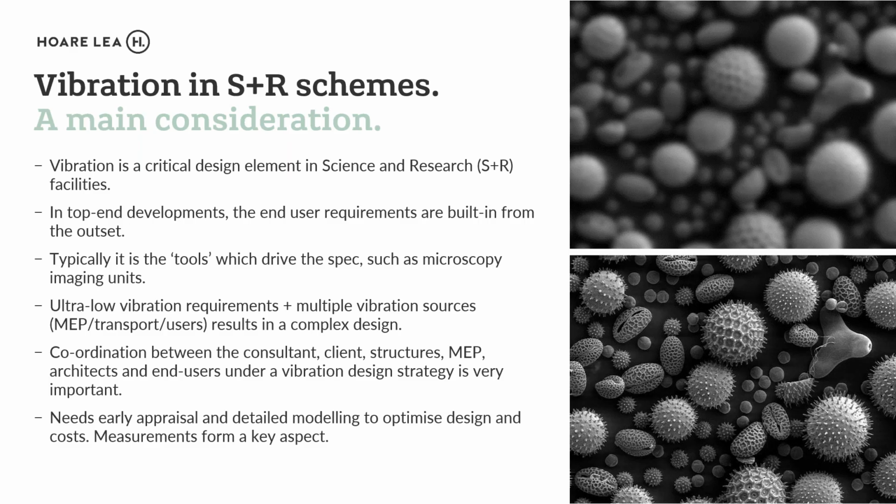In these ultra low vibration facilities, where we have levels of vibration far below the level of perception, it's not just environmental vibration that actually affects the end result. It's a combination of everything. So that could be MEP, noise, if there's any noise generating activities, and also footfall, users walking around the complex as well. So that becomes a very detailed assessment, quite a holistic form of assessment, a design challenge that vibration presents in these science and research facilities.